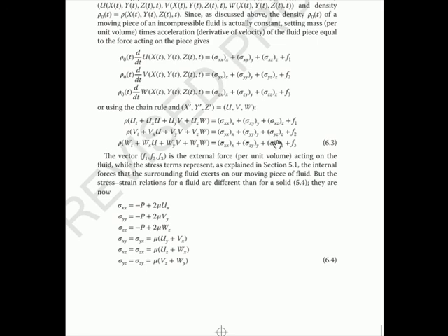You just get rid of the W equation and the Z derivatives and the W here. And it's pretty obvious changes. Just assume W is 0, and so there's no flow in the W direction, and the derivative of everything with respect to Z is 0, and it reduces to